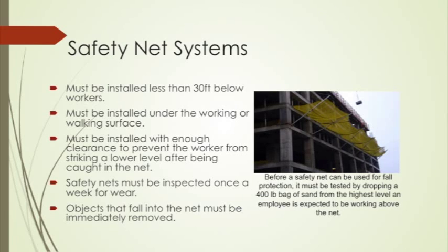Before a safety net can be used for fall protection, it must be tested by dropping a 400-pound bag of sand from the highest level and employees expected to be working above the net. Safety nets must be inspected once a week, and objects that fall into the net must be immediately removed. The maximum size of square opening in the net cannot exceed 6 inches across.